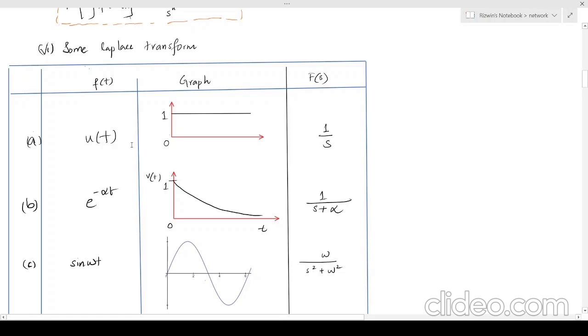So the magnitude will be E and the value starts from t equal to 0. Now if we take the Laplace transform of the unit step function, we get 1 by s. If it has a magnitude of E, then the constant is retained, and the Laplace transform of u of t will be 1 by s again, and E by s will be the complete transform of E u of t.